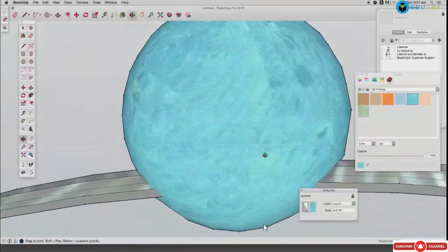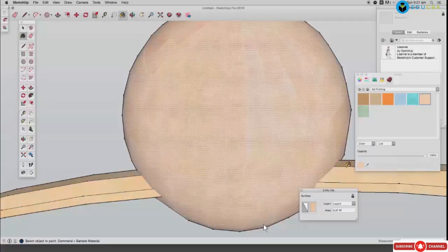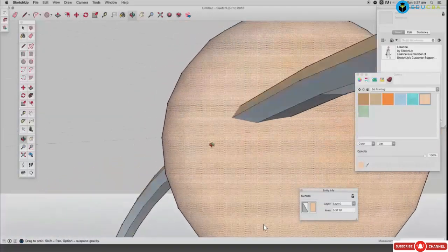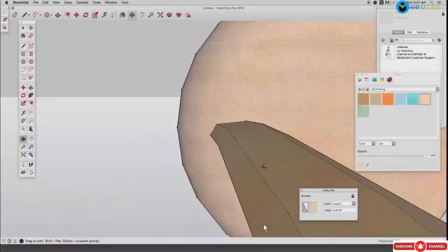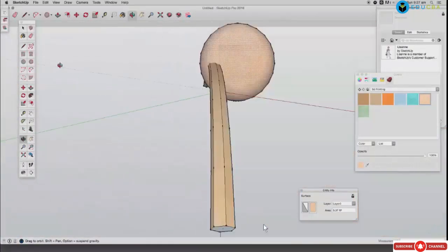We know the shapes are created with faces and edges. Individual faces can be colored, textured, or even rotated separately, irrespective of the object position. Just select one face of this tube. Let us try to rotate it.